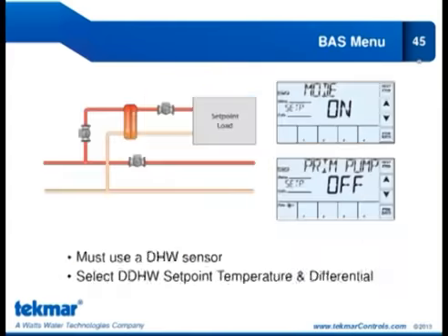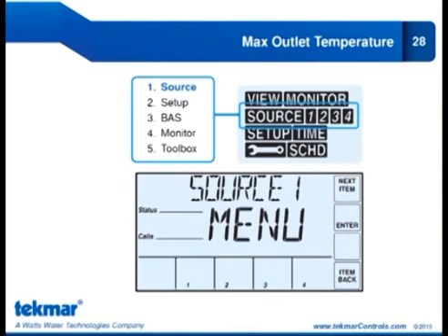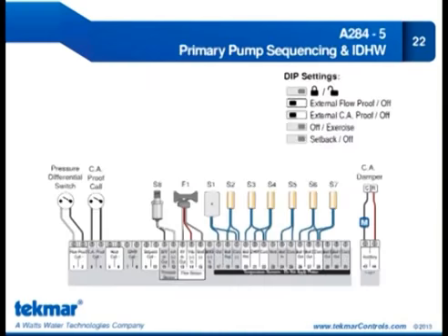And also what the proof is, right? Because in this case you look at 275. If you're doing combustion air control for a damper motor, or you're doing flow proof, then you have to assign what you want to use a proof for, combustion air proof or flow proof? Well, the 284 supports a proof for combustion air and also for flow proof.